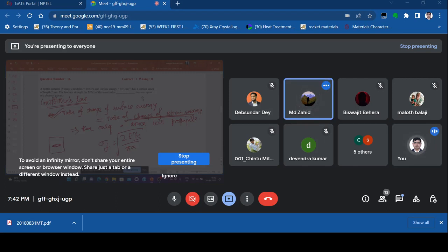But sir, it is a surface crack, no? Yes. Surface crack means a is already given, so you have to put just a. If it is a through-thickness crack in the middle, like this I have shown here, then you have to halve it. You could have used 1, but it is a surface crack already. So the crack is something like this. So this is a. You don't have to change anything. Okay, yes, sir.